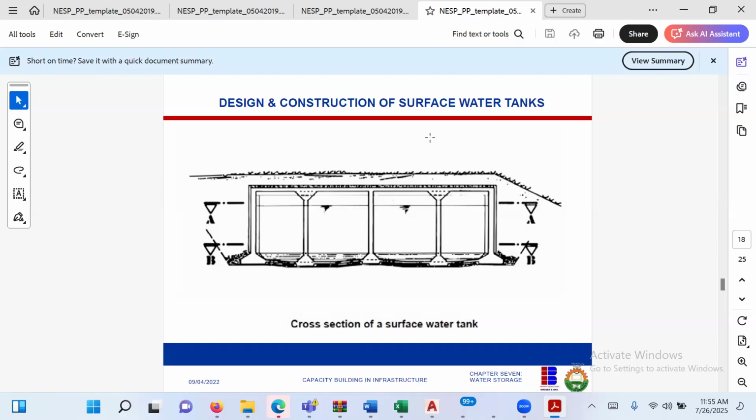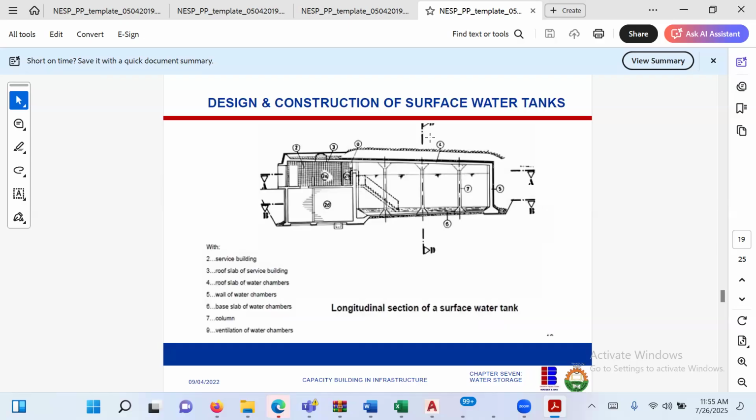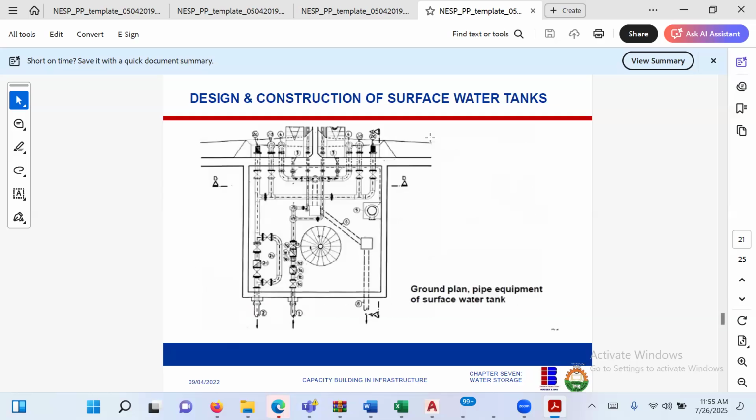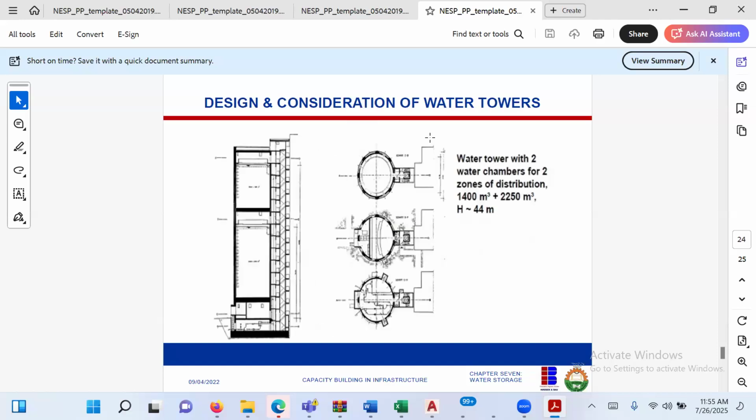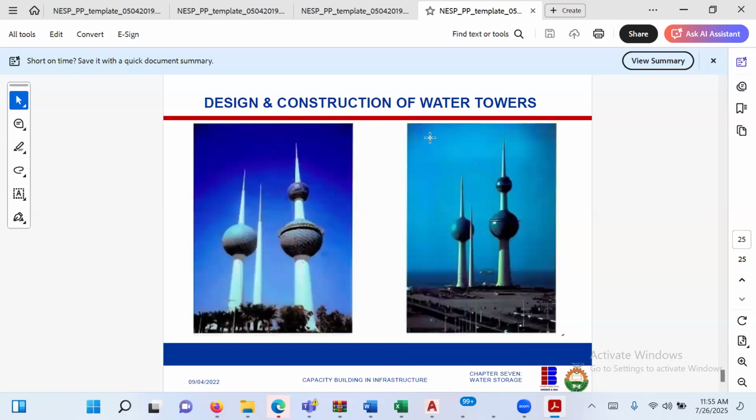Water hammer can be destructive. Yes, can be very, very destructive. Avoid it. Always have dissipators. Good. So this is another design. Just study it at your free time. Depending on the layout, depending on the location, you should be able to come up with a customized solution. In the Arab world, of course, we know they build things like this, both for aesthetics and because they have money to build this thing. So these things can be very, very expensive.